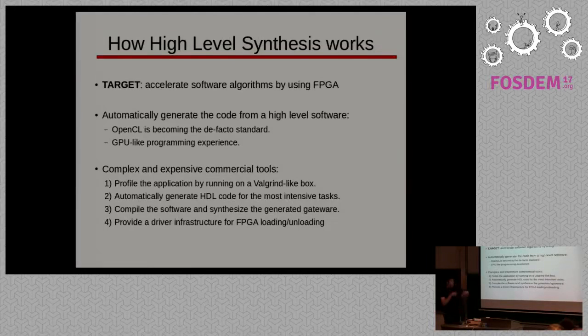Then the software part is compiled, and the hardware part, the gateware part that is going to be deployed in the FPGA, is also compiled and generated. Another piece of these tools is a special kernel module that is in charge of loading and unloading the FPGA's cores as they are demanded by the algorithms.